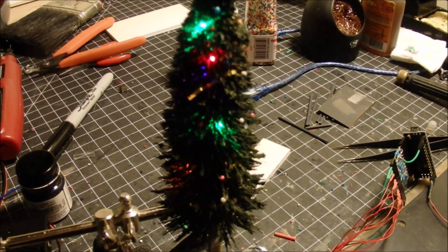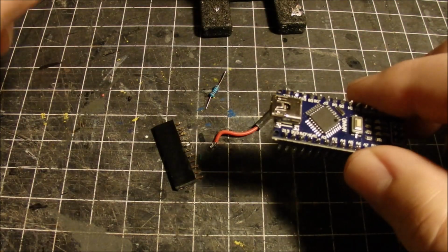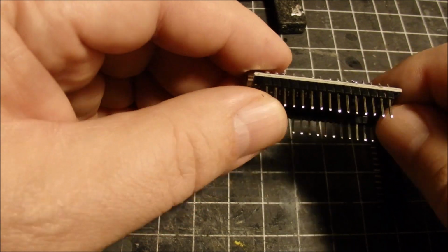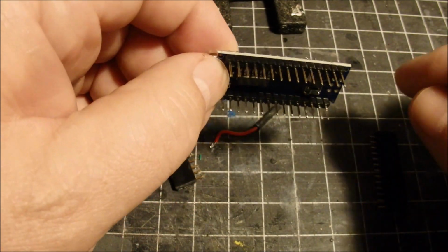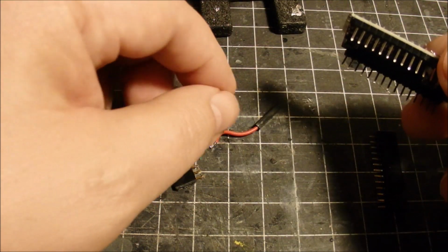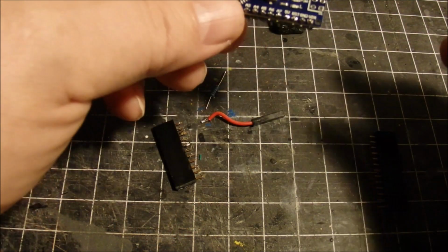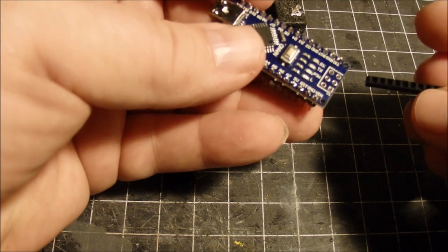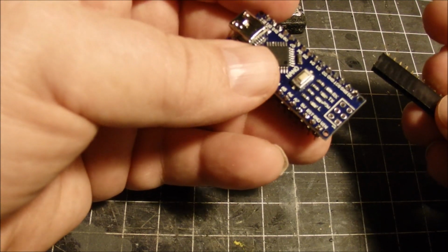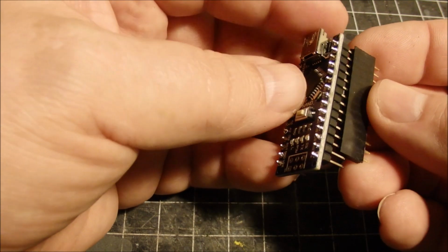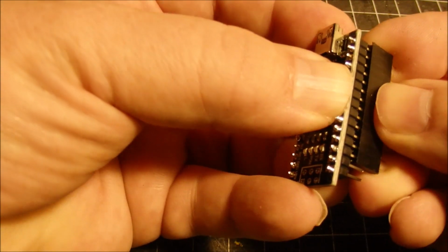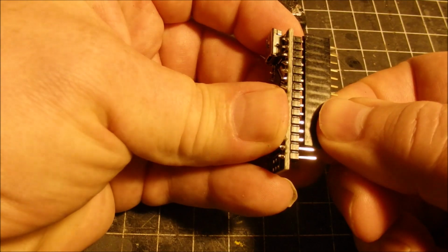Just wanted to briefly go over the setup I did with the little nano board to plug in all the little LEDs. I used a bit of these little breakaway sockets here, and plugged that in from digital pins 2 through 12 to get my lights. So that kind of plugged in like so.